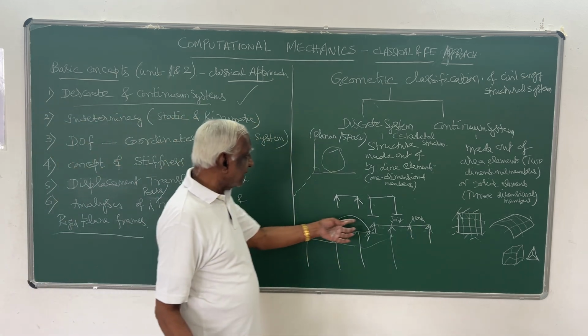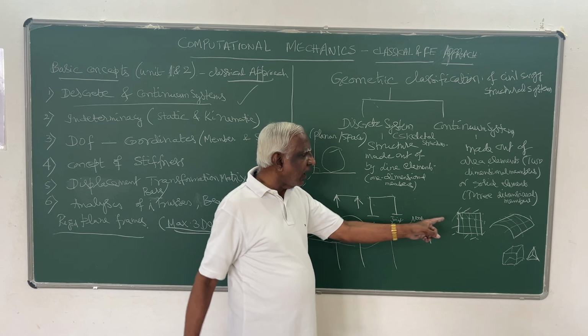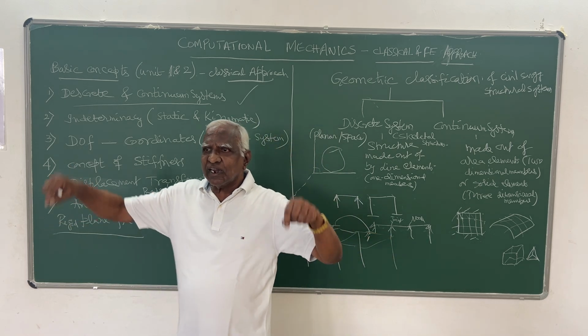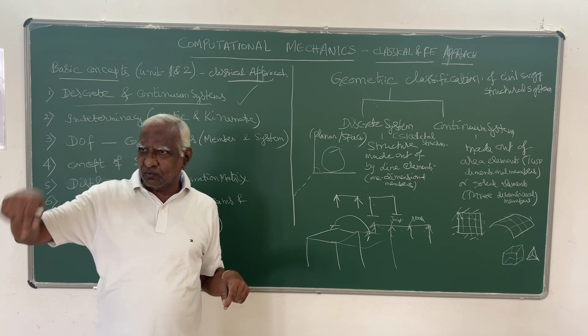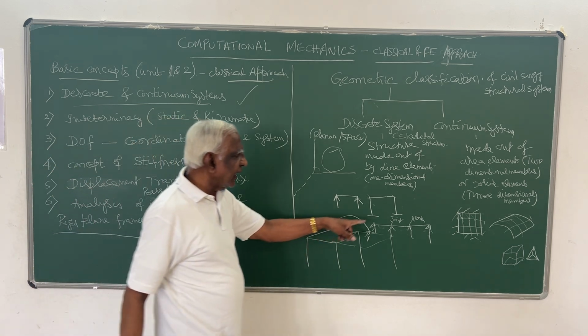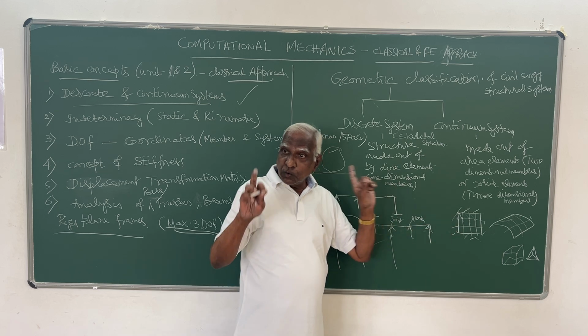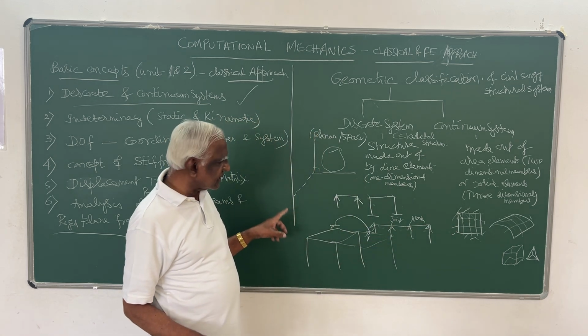If a load is acting either on the entire length of the line, or the entire area, you are going to consider the equivalent resultant load acting at the joints. Right? So during analysis, this is another important thing which we have to consider.